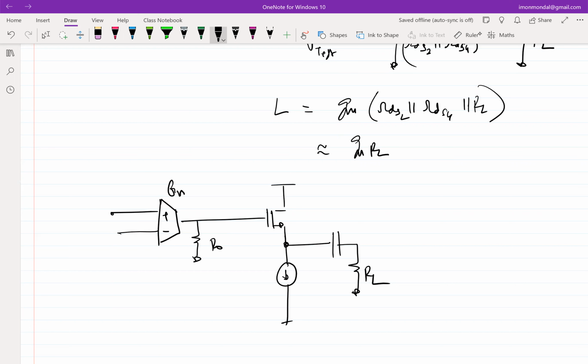And you take this to be your V0. And you might want to also get rid of the capacitor if you are confident that this transistor, let me call this M5, can supply the appropriate current to the RL. It will load M5, but if you size M5 accordingly, it can still provide the adequate current. And this becomes your V0.